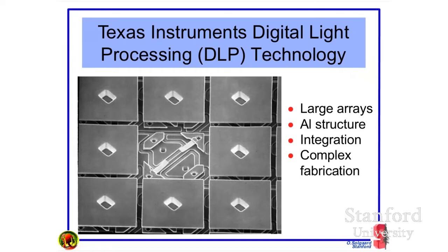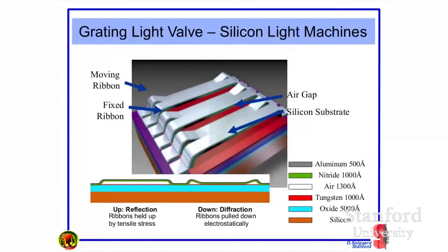That substructure is very interesting, but again, it's a spring. You can see those little white pieces. Those are springs that connect it to the mirror, and the mirror rotates on the spring. Underneath there's all kinds of other things. There is integrated electronics in this particular chip, and that's a theme that I will return to on occasion. So again, we have this mass on the spring.